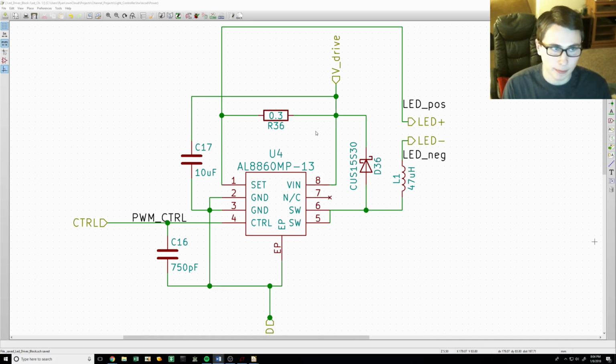In this case, the value of this resistor sets the maximum current output of the controller, since it's truly regulating the voltage drop between the V-in pin and the set pin. Changing this value will adjust the maximum current, which can then be adjusted from 0 to 100% using the control pin. We'll leverage this ability to change the maximum current if there's more white or infrared light required, since this value can be tweaked to push the LEDs to their maximum of 1000 milliamps.